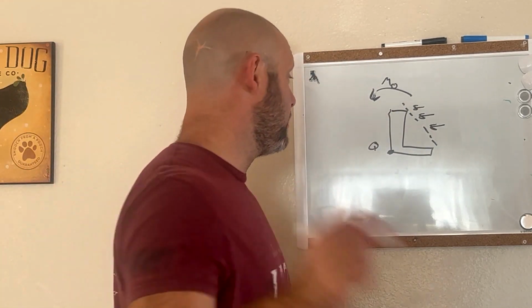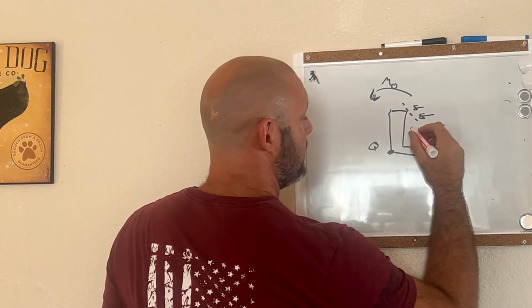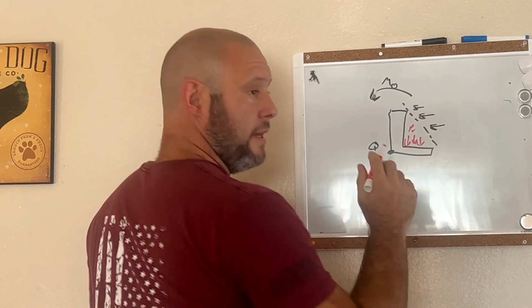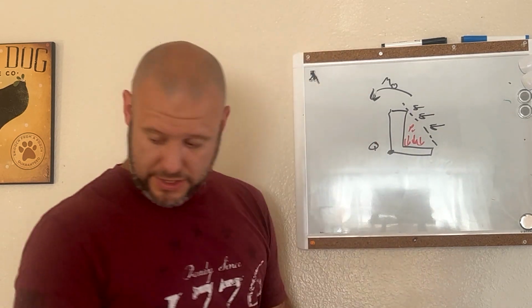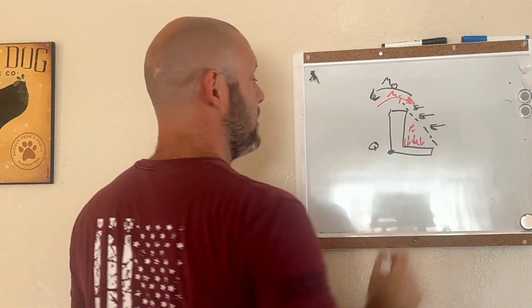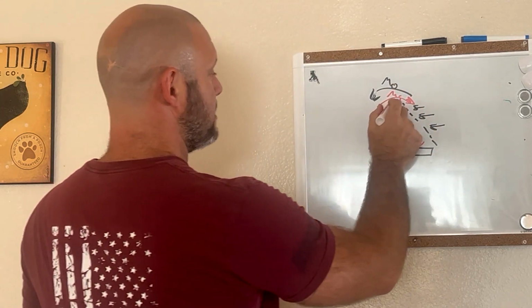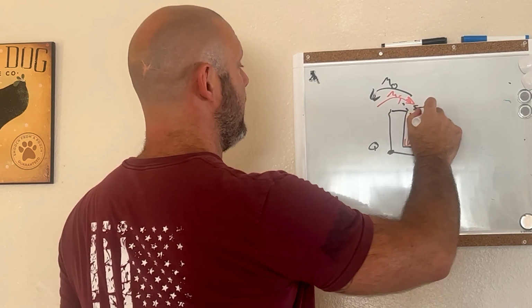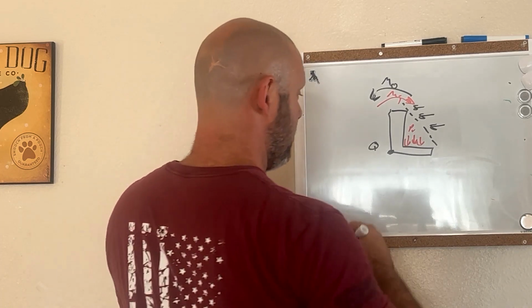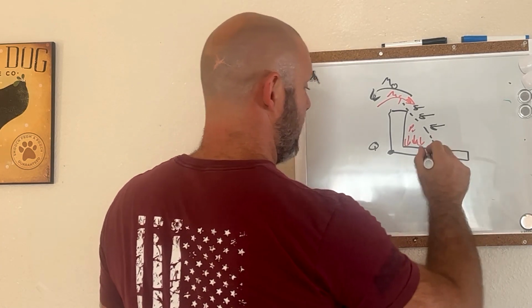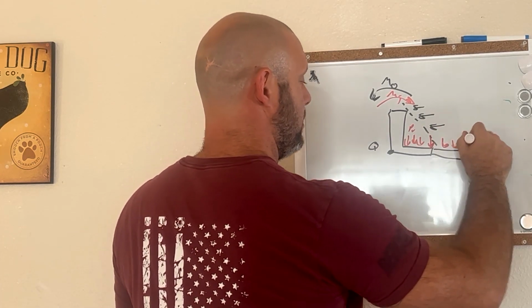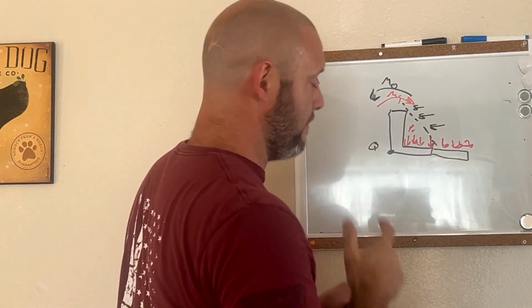In kind, they're also calculating how much of this passive pressure down on the footing is the stabilization moment, which they label as the other way, MS. Essentially, they're making sure that this stabilizing moment is greater than or equal to the overturning moment. And they do that by extending the footing further and further, right, until all of the soil forces here resist that overturning moment.